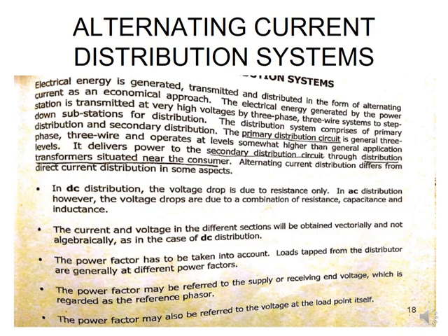Mainly, in your DC distribution, your voltage drop, if you remember, was only resistive. It was always just R ohms. But in AC systems, the voltage drop is due to a combination of your resistance, your inductance, as well as your capacitance. So it's impedance in this case.